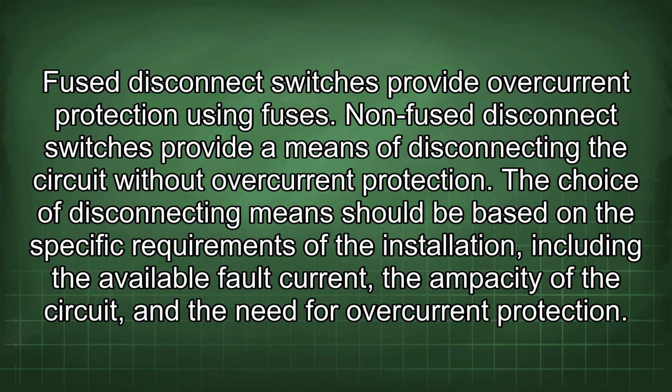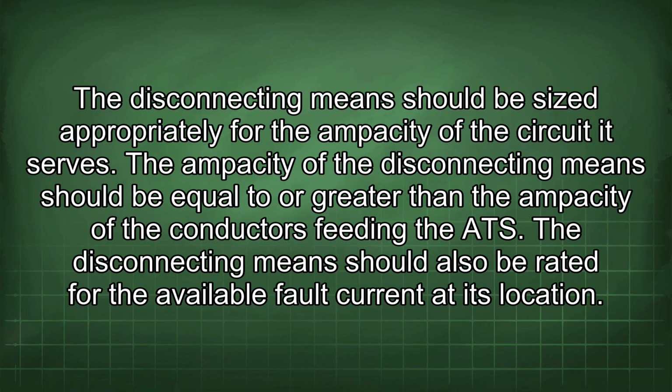The choice of disconnecting means should be based on the specific requirements of the installation, including the available fault current, the ampacity of the circuit, and the need for overcurrent protection. The disconnecting means should be sized appropriately for the ampacity of the circuit it serves.